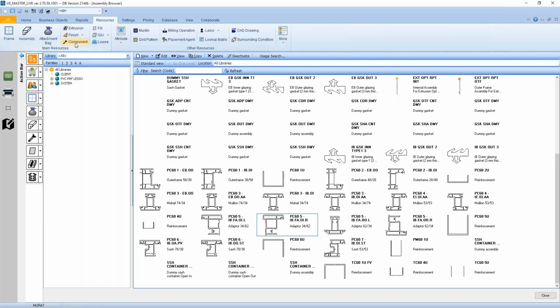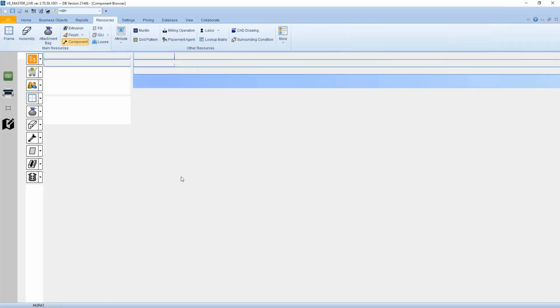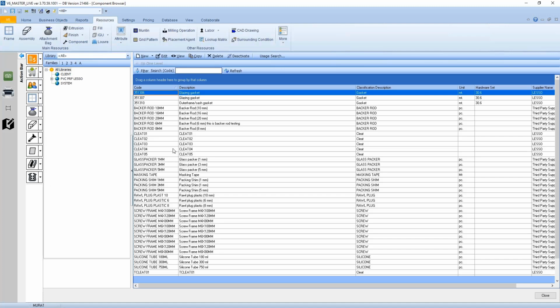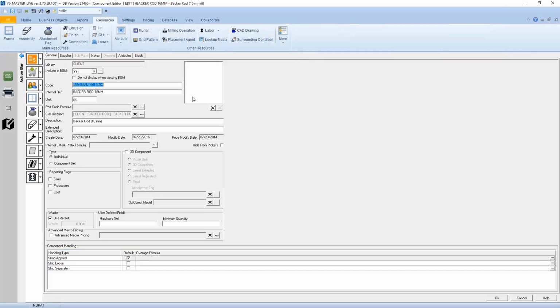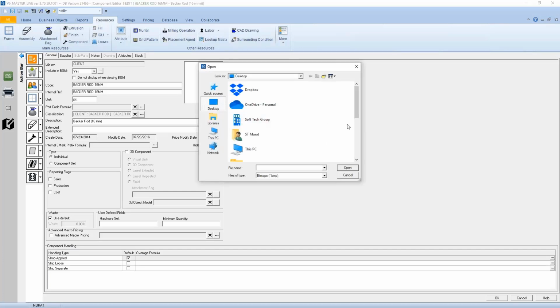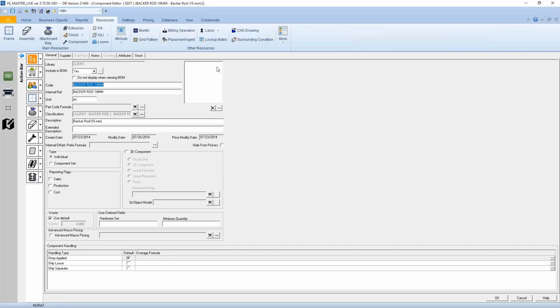In that area, another enhancement is about the components. Now we can add a picture to components as well. If I open a component, here we have this thumbnail button. You can click and pick one bitmap from the list, click OK, and then it appears here. This picture also has a link in our quick report, so you can print them.